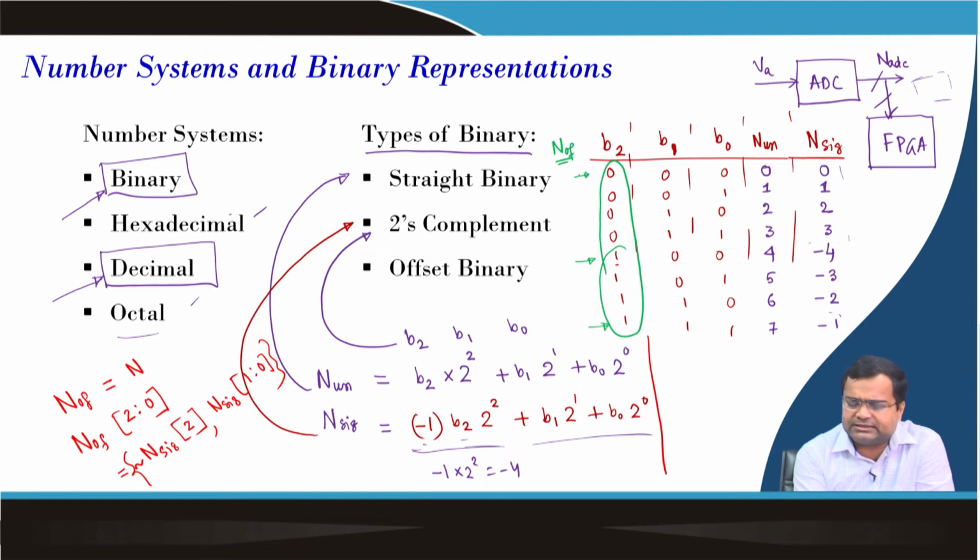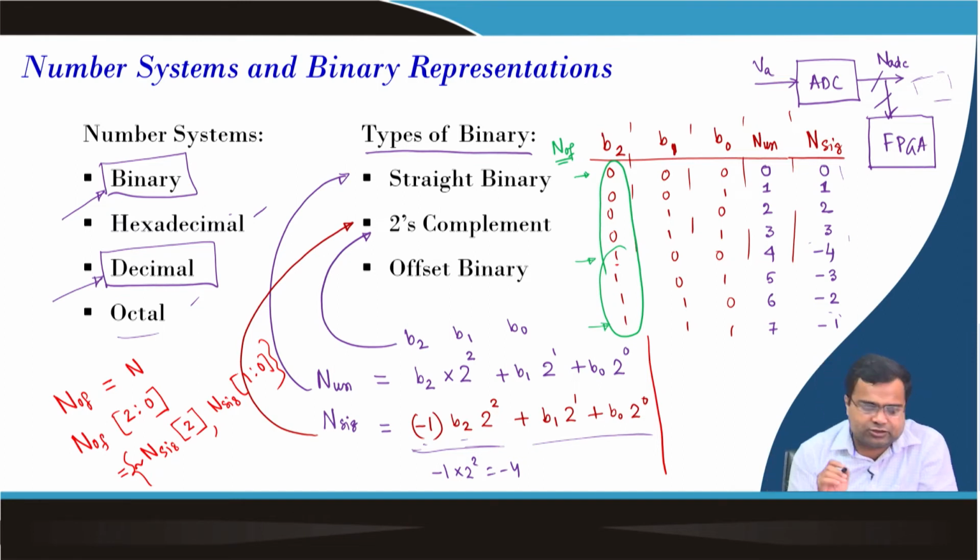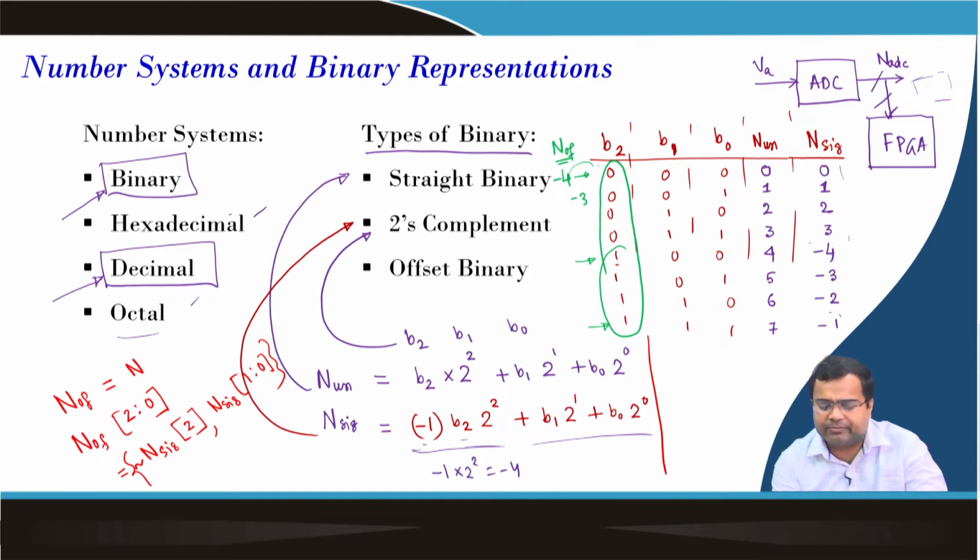So, you can represent a negative bipolar number by suitably making the offset, that is why it is called offset binary. So, in offset binary, this will be the maximum negative number. It starts with the maximum negative number, this will be -4, because 1 all 0 in 2s complement corresponds to -4.